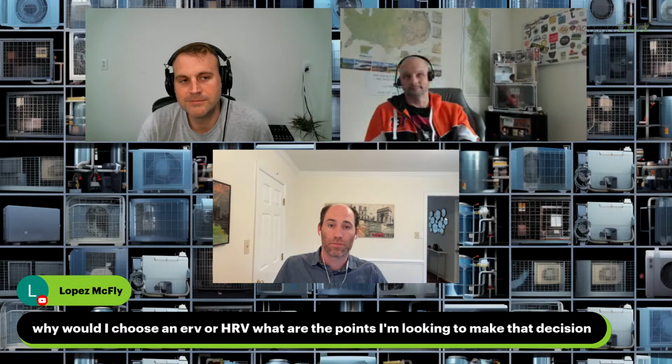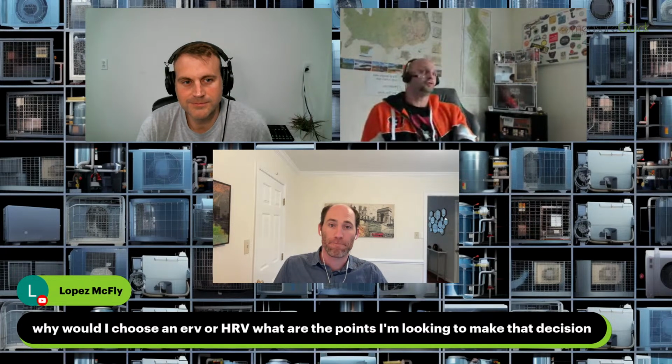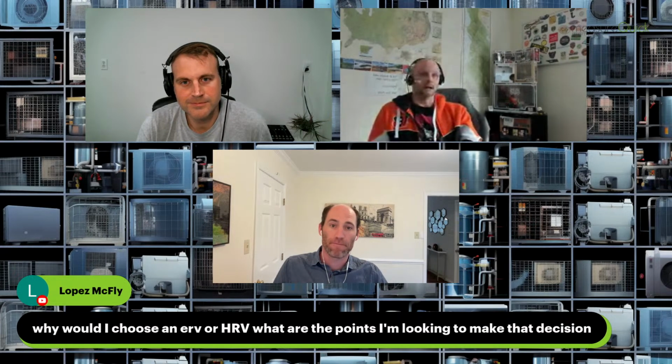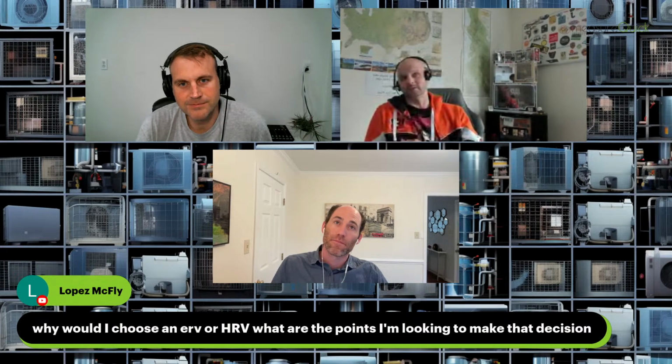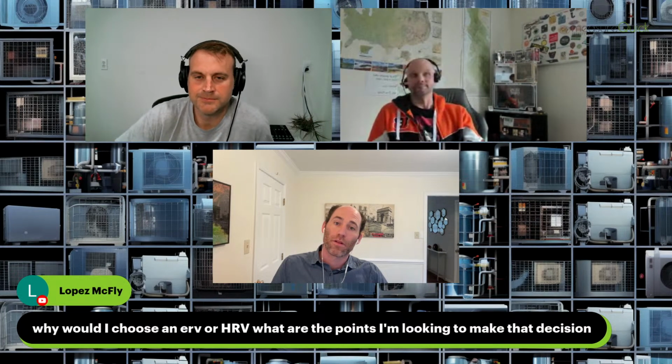Like, is there a reason where you would choose that over one? Even in a market, say, where we're not in too high of a moisture market or climate zone, I still think the choice is ERV. As a designer, I don't have a good reason to ever pick HRV over ERV in any given situation.